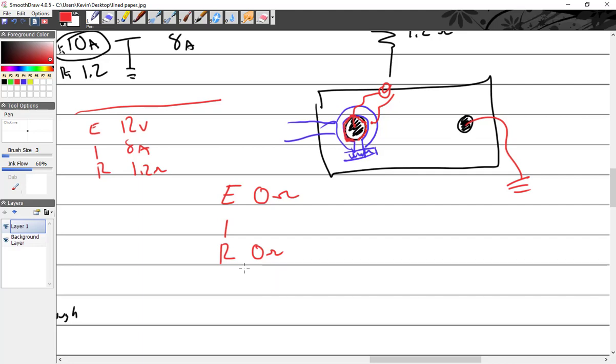But then I say, Brett, hit the starter. The starter's going to draw, let's say, 100 amps. And turn the lights on too. Now I gotta get the subs going. 100 amps, and I get a 4-volt drop across there. Is that something I wanted to see? That is not. What is my resistance? E = IR. What is my resistance? 0.04.